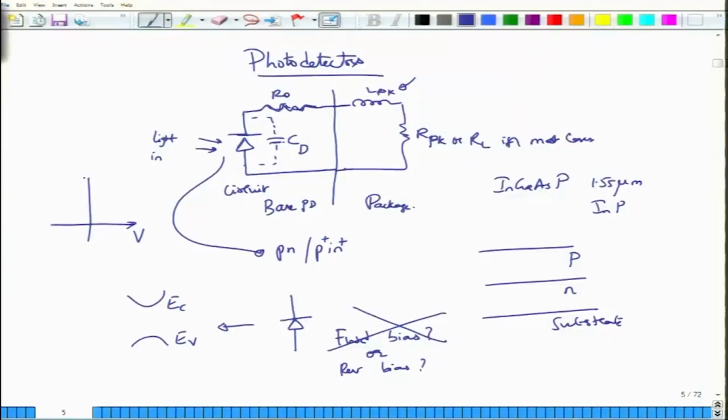But now when you apply light, there is a good chance that these carriers will be recombining, okay. Even before you apply light, because of the forward bias, a large amount of current is flowing, right. So, if you look at the current to voltage characteristic of a photodiode, you would see that just a small amount of bias is sufficient for a large current to flow through. And when you launch optical signals, instead of optical power being absorbed, you actually start getting more optical power, and the current would actually reduce, okay.